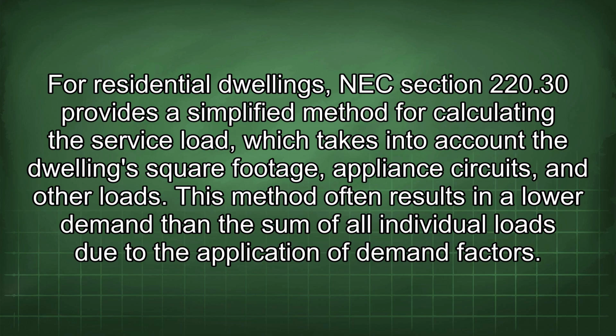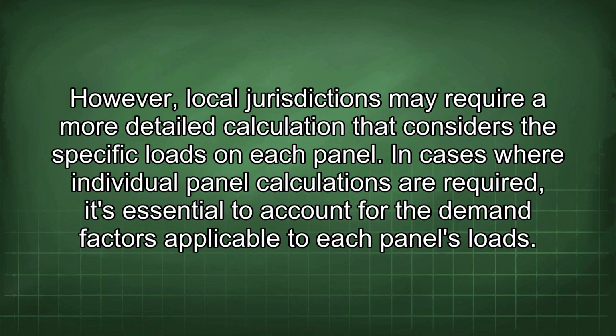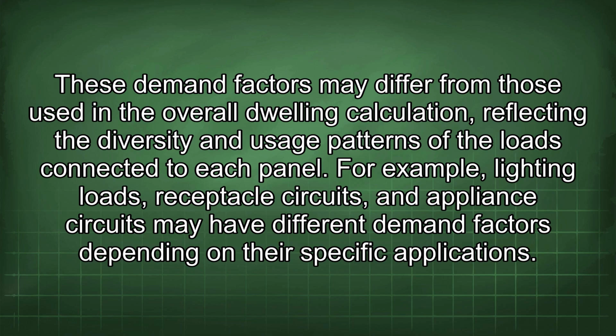This method often results in a lower demand than the sum of all individual loads due to the application of demand factors. However, local jurisdictions may require a more detailed calculation that considers the specific loads on each panel. In cases where individual panel calculations are required, it's essential to account for the demand factors applicable to each panel's loads. These demand factors may differ from those used in the overall dwelling calculation, reflecting the diversity and usage patterns of the loads connected to each panel.